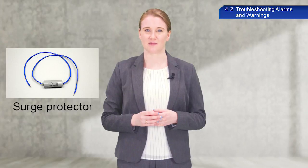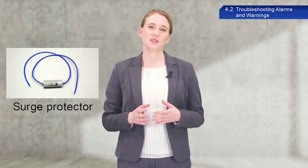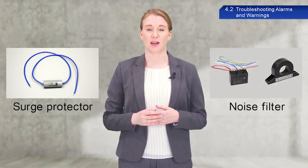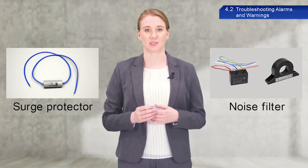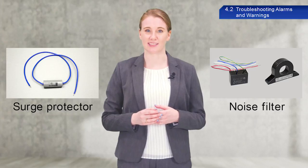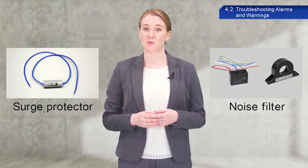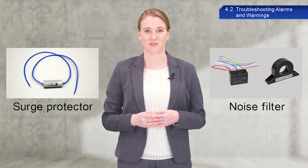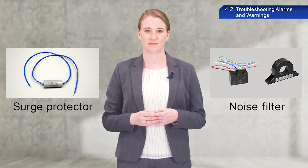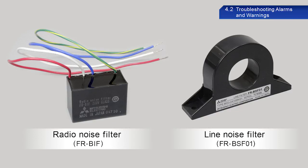noise generated. If noise generated by the servo amplifier is causing issues, install a noise filter into the servo amplifier power circuit. In this training, you will learn how to install a radio noise filter and a line noise filter. Use either of the two filters that is applicable to the situation when resolving actual noise issues.